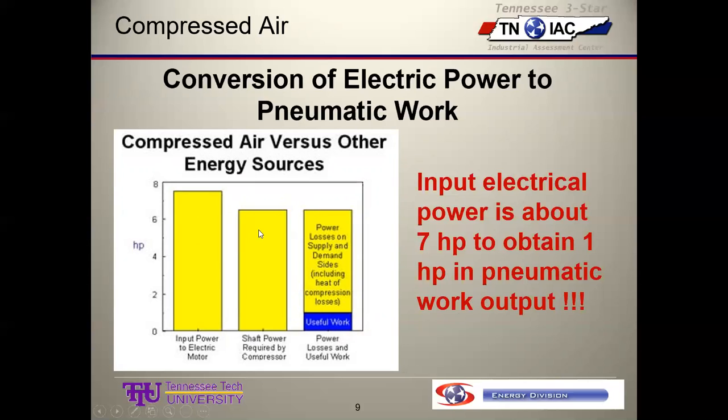And of that energy, there are power losses and useful work. The useful work is in terms of the pressure. In the process of compressing the air, it gets really hot, and we typically throw away the heat. Well, this is maybe 15 to 20% of the energy, and that gets used in terms of pressure. And this is the amount of energy that we throw away in terms of heat. So you see, we put this in and we get this out.